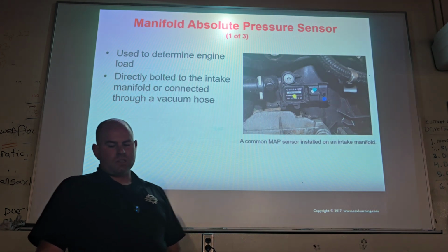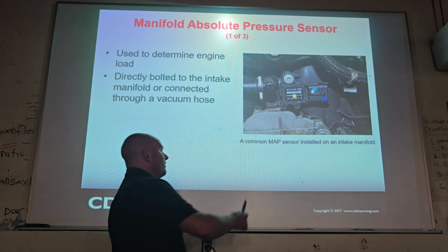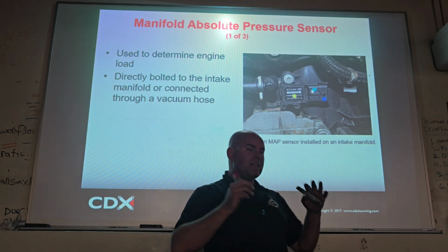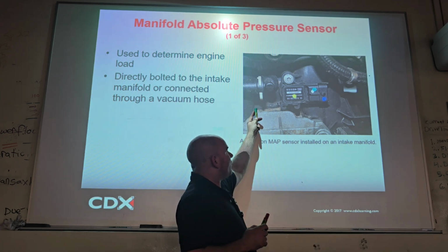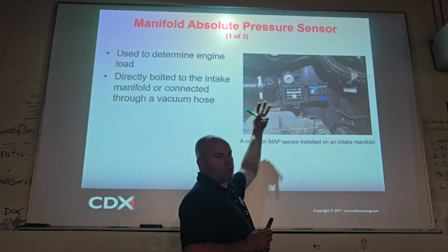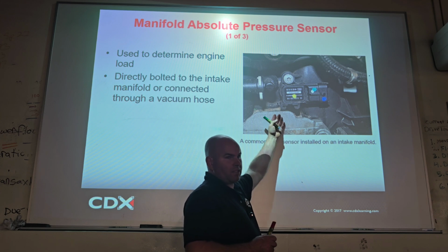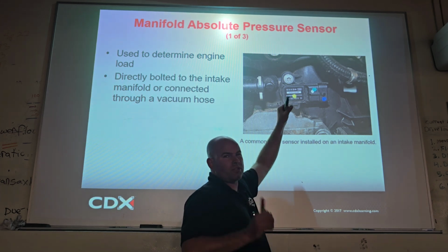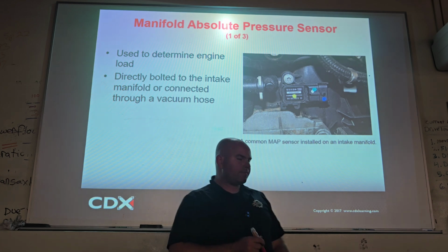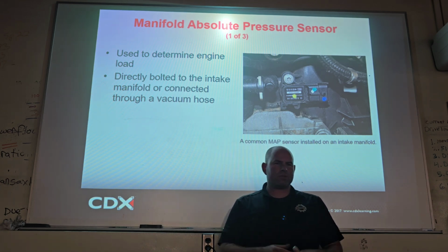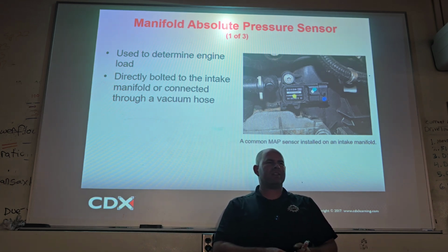Cool. And then with MAP sensors, this is the exact same thing as a transmission fluid pressure sensor. It's a 5 volt diaphragm, right? It's 3 wires: 5 volts, ground, and a signal circuit, and it's a pressure transducer, the same. Why is this in transmissions? It's a MAP sensor. What the heck do we want to know about that for?